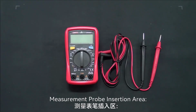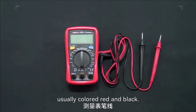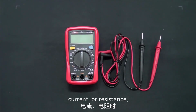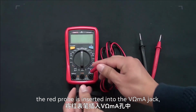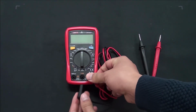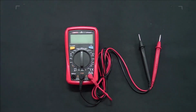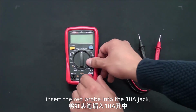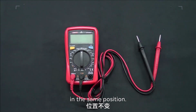Measurement probe insertion area. The multimeter is equipped with 2 measurement probes, usually colored red and black. When measuring voltage, current, or resistance, the red probe is inserted into the volt-ohm milliampere jack, and the black probe is inserted into the COM jack. If measuring high currents, insert the red probe into the 10 amperes jack, while keeping the black probe in the same position.